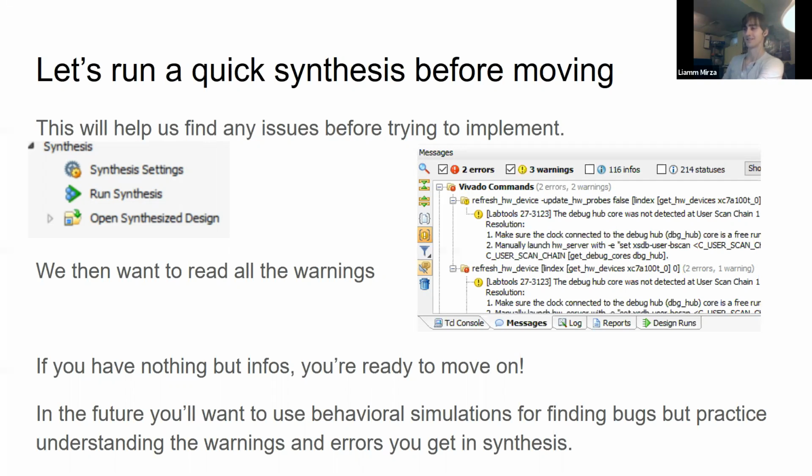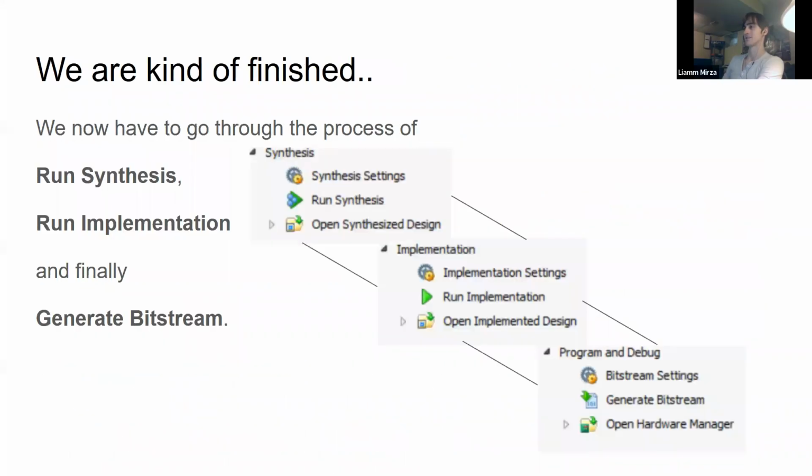Yeah, I think I messed up my Vivado instance because I was annoyed by these pop-ups and I kept pressing that button. So every time I ran a synthesis, it would open up an implemented design. I was like, I don't want this anymore. It would automatically go through this whole implementation process that I don't want, when I really just wanted to generate a bitstream at the end. But it can happen. Just don't ever press the don't show again checkbox, guys.